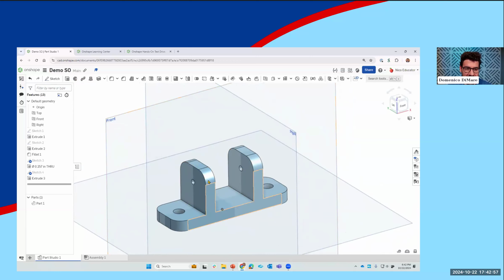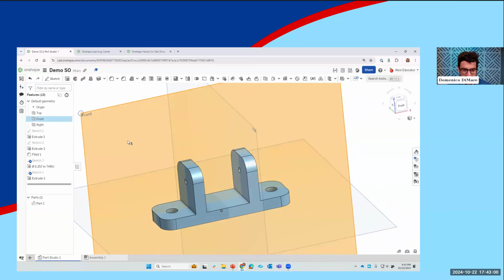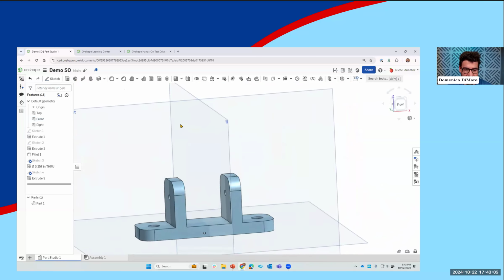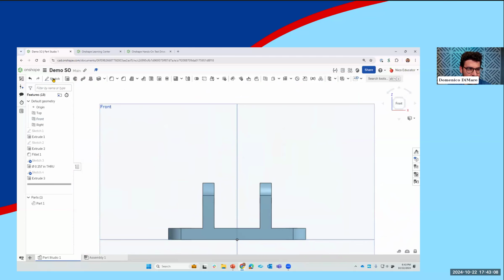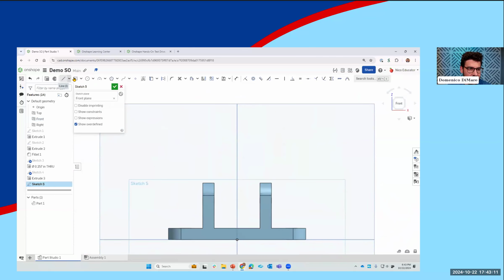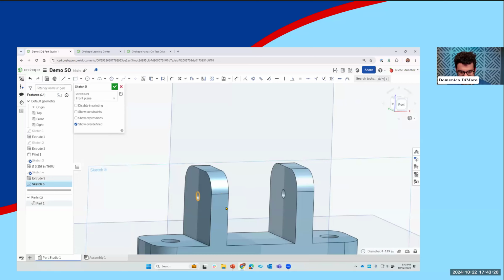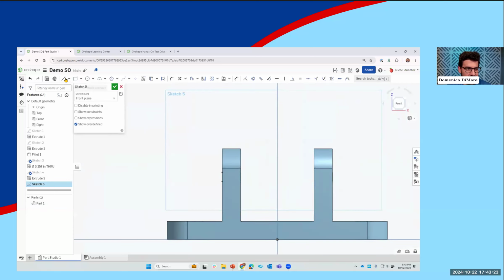Maybe we need to add the actual round pulley part in here. So I can go in and start sketching on this other surface. And I can go ahead and create. I'm going to make this a little bit differently. I'm going to use another feature here in OnShape called the revolve feature. So instead of extruding this part, I'm actually going to revolve it and create basically a circle. So you're going to see what this looks like here, a disc rather, in a second.